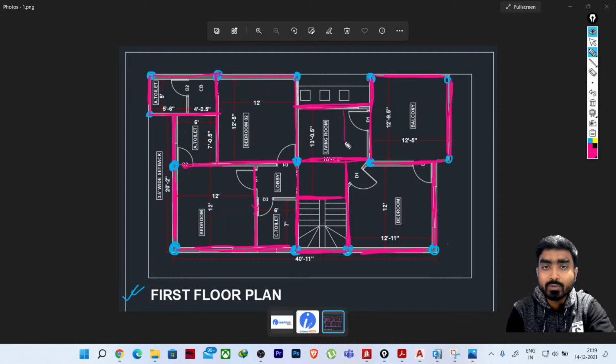So in this place, we need to have a beam in the ground floor, that means in the plinth level, right? At this place. And obviously we need to have this beam to connect these two columns. It will be kind of a tie. So let us now just do this.